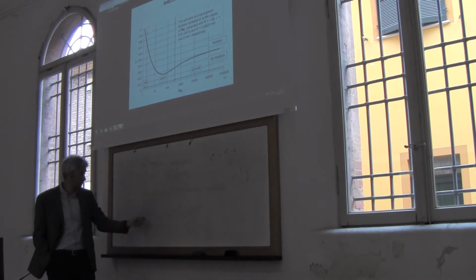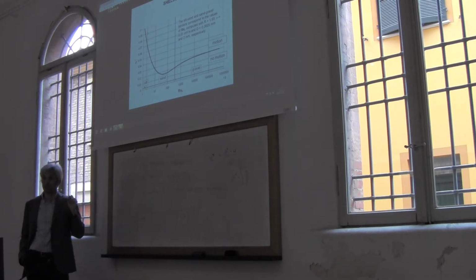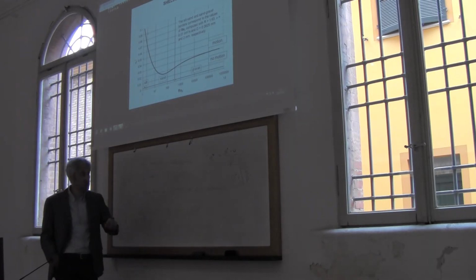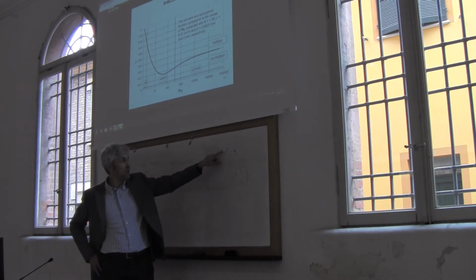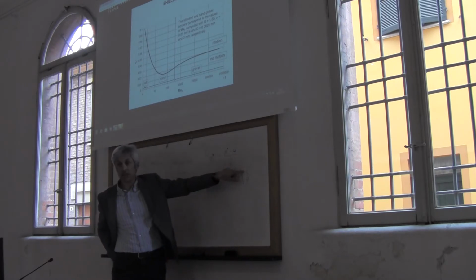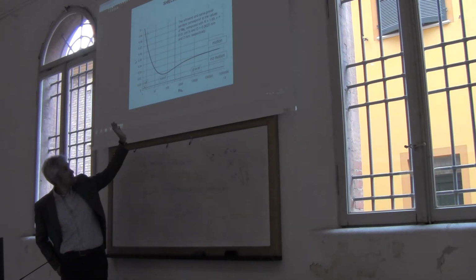So basically this applies where there is a lot of turbulence, for high values of the Reynolds star number. High values are reached when you increase the shear velocity. And the shear velocity is increased when you increase the friction factor, which means velocity of the waves. So he found that for high velocity, it's indeed constant.